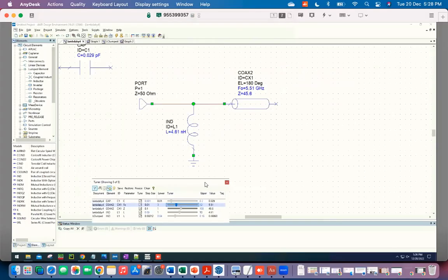Actually, sorry, I made a mistake here. Can someone tell me why this is not a good boundary condition for this particular resonator? So the problem is that we were working with a lambda by 2 resonator with both ends which have to appear as open. This inductance to ground is more naturally a short circuit. So it will behave better if this was a lambda by 4 resonator.